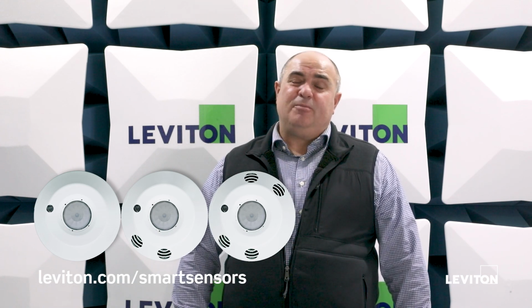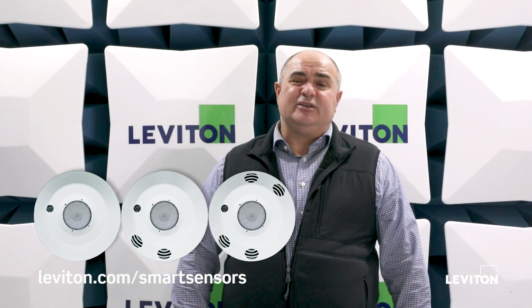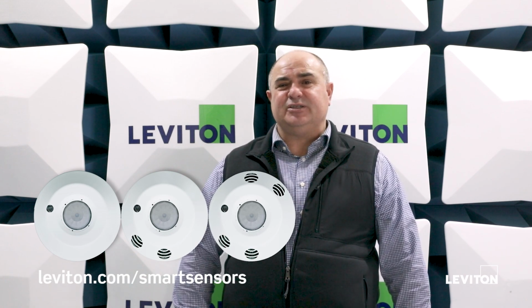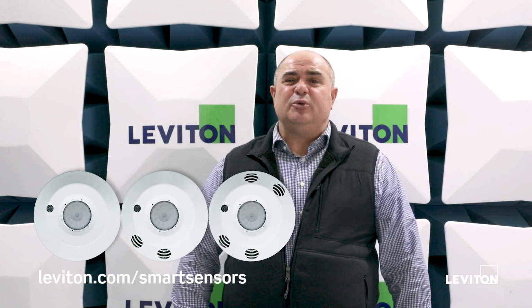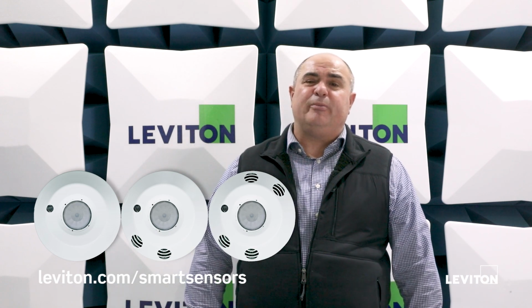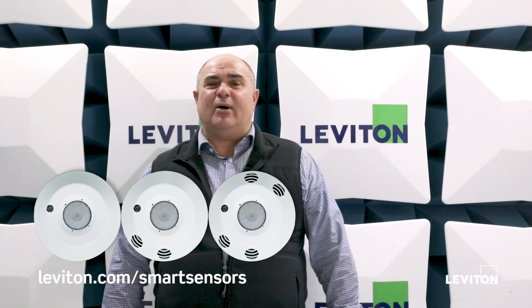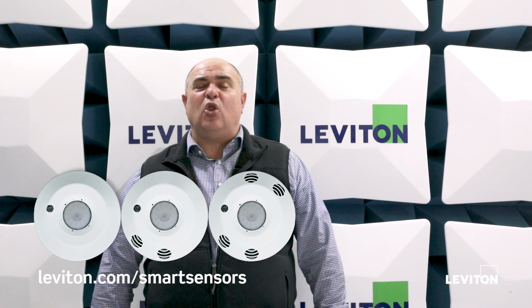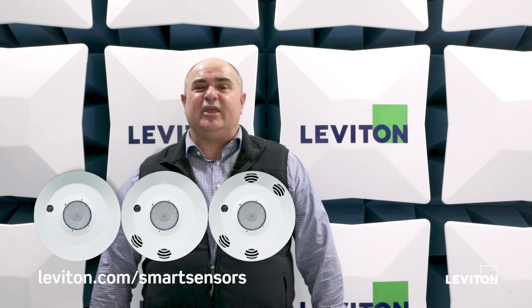Now, the light pipe accomplishes a couple of different things. The light pipe allows you to use the sensor in either open loop or closed loop applications. In open loop applications, we would tend to mount the sensor in the room in a way that would allow us to install the angled light pipe, where the angled light pipe will now actually not be looking at the floor of the actual room and give you the total of the natural light and then the artificial light.